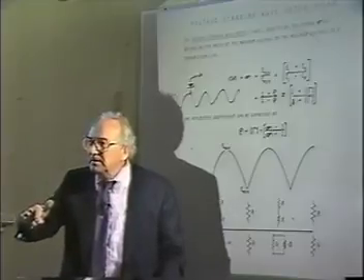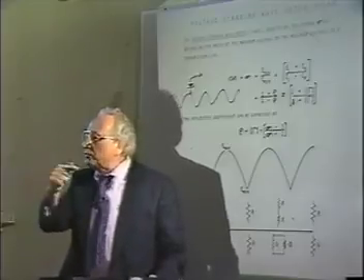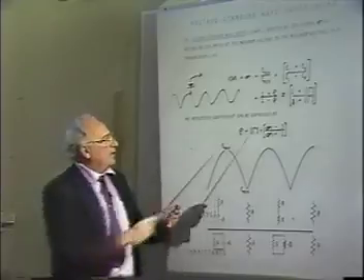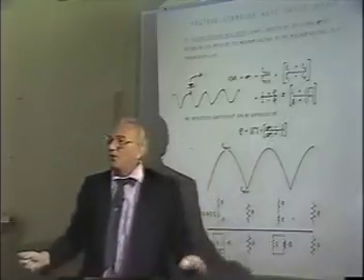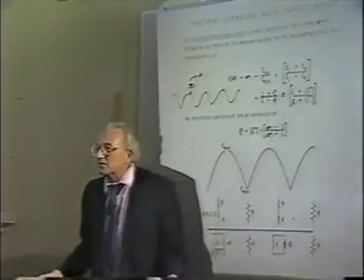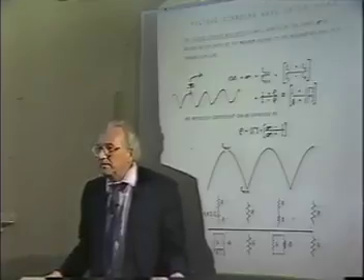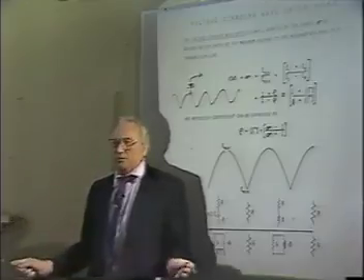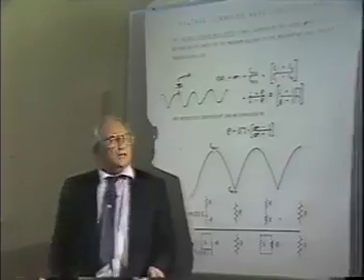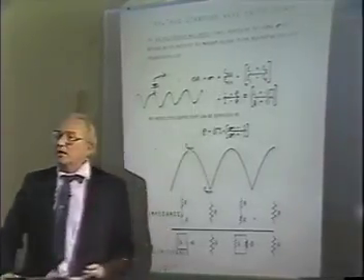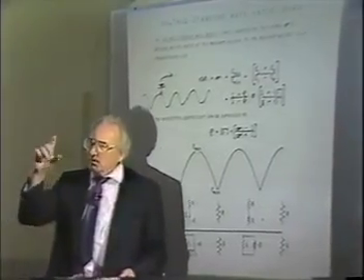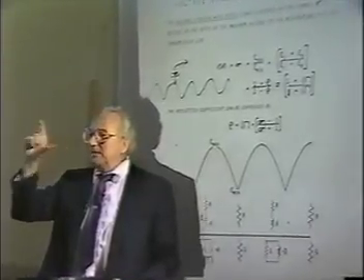And we know that only happens when you have waves traveling back and forth on the line. But if this is 0 and this is 0, are there any reflected signals? None. So when there's no reflection on the transmission line, these two signals are equal and the voltage standing wave ratio is 1. The maximum voltage is the minimum voltage.